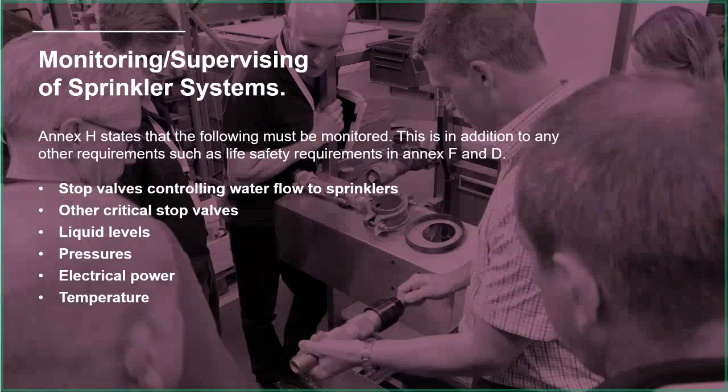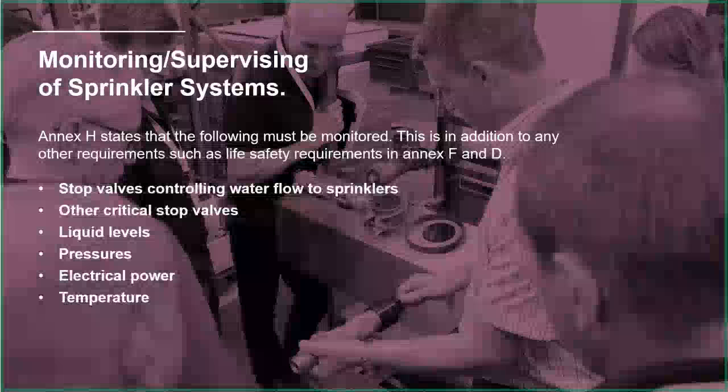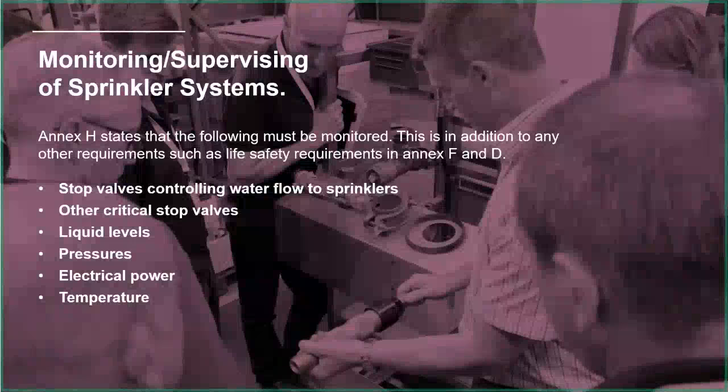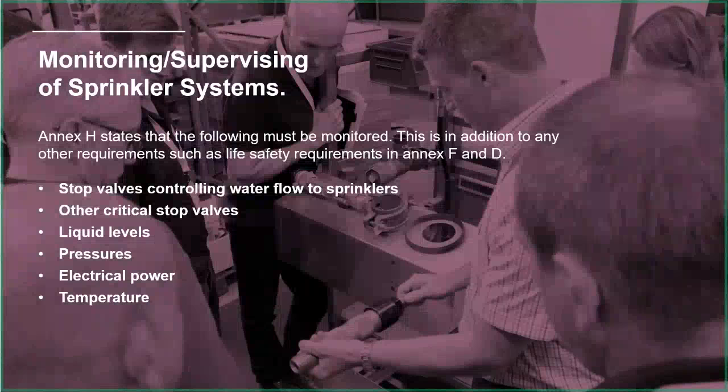And finally, temperature. We don't want any water to freeze. We don't want our fire pumps to freeze up. So there are going to be sensors that are monitoring the temperature of the water in the sprinkler tank, for example, and the temperature in the pump house, which are going to alert us to any problems. And what that's really doing, essentially, is saying that the heating system has failed.